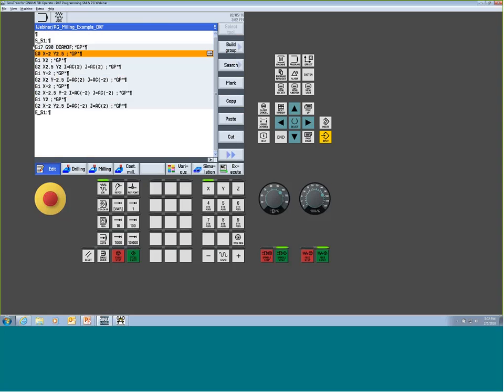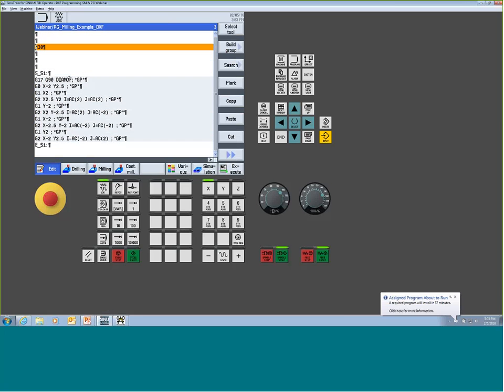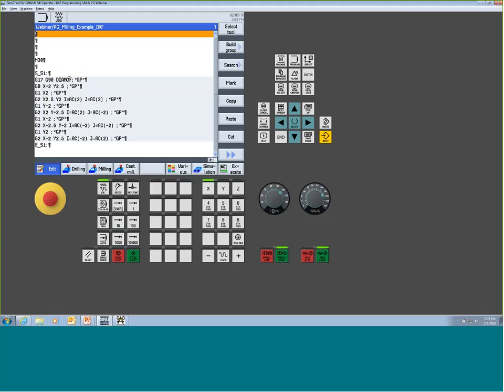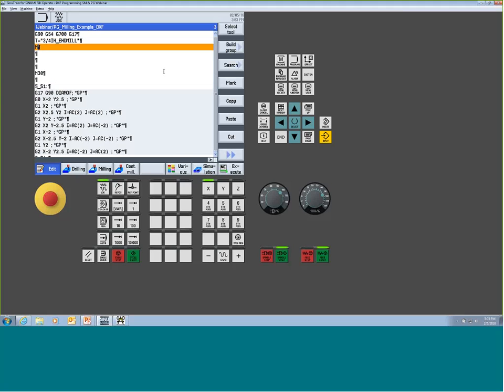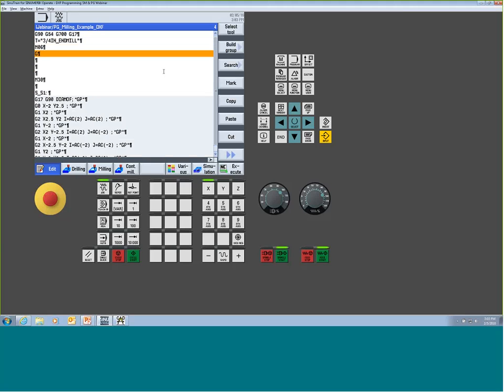All right, so the start and end labels, what does that allow me to do? Now this allows me to start calling up and using the feature somewhere. So, if I was to now start literally building a basic G-code program, I'll move this down. Generally what I do is I create my shapes below my M30 or end of program. Here we can do some atypical program structures: absolute, work coordinates, unit of measure, maybe my orientation plane. Let's go grab a tool, the normal G and M code. So we're going to grab a half-inch tool, do a tool change, maybe tell it my feed strategy, fire up our spindle.